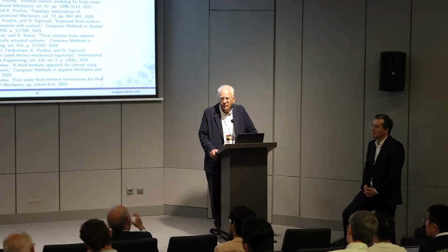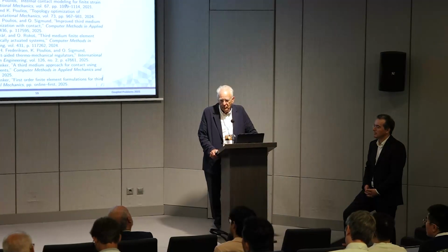In the particle finite element method, we also have a contact domain between bodies, and this is automatically detected at the mesh generation level, meaning that you don't need to mesh the whole domain. Using something like Delaunay, you could identify your contact region. This will reduce the third domain to the actual contact region. Would that be possible, particularly for metal forming applications, which was the object of interest?